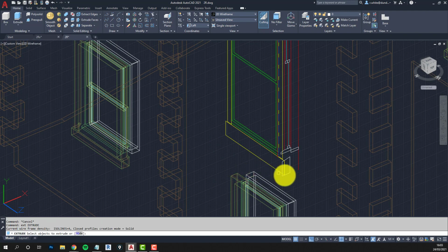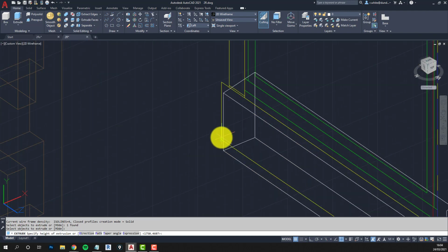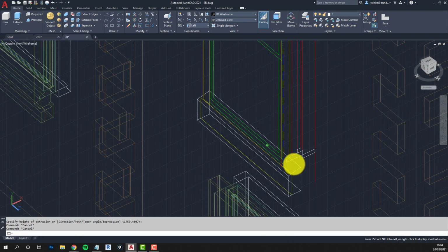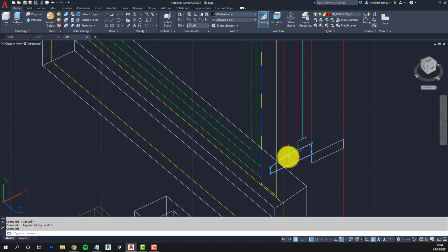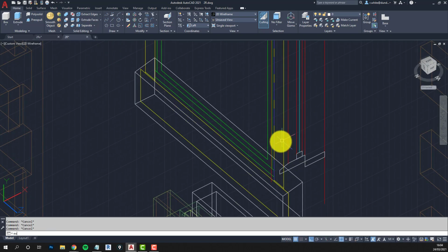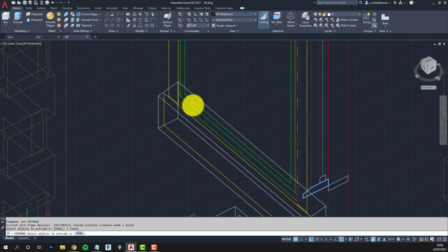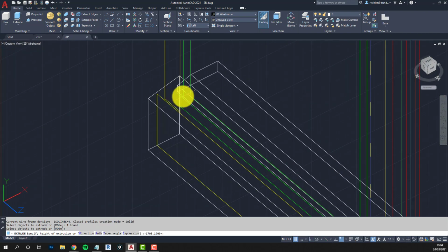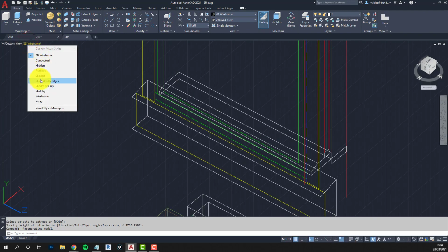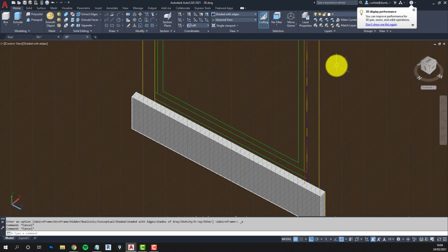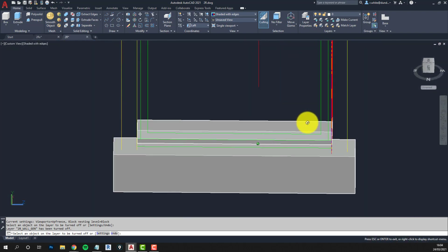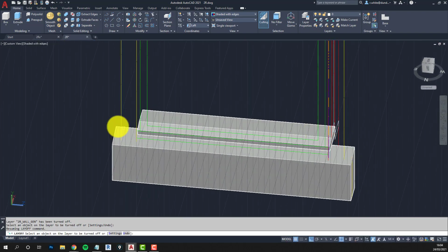Okay, so let's extrude that. May as well start putting in a few 3D shapes as we go. Okay, the sill here is in the kind of correct position already, so we could actually just use that as is. So let's just extrude that. Okay, and this is going the full length of the inside of the window. Okay, let's just shade that so you can see what's happening. Oh, we need to get rid of the wall. We don't want the wall layer visible. So I can see we've got our two components of them already, and the distance here, same as the distance here.